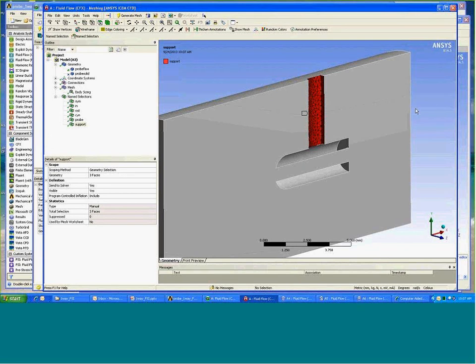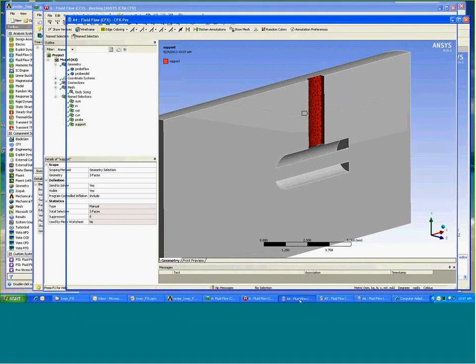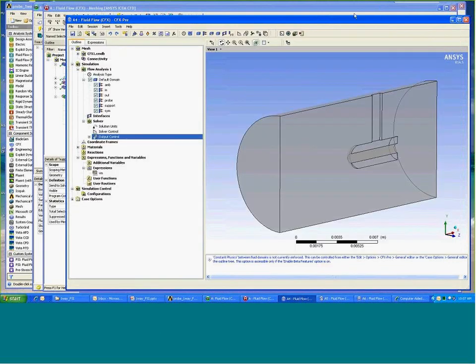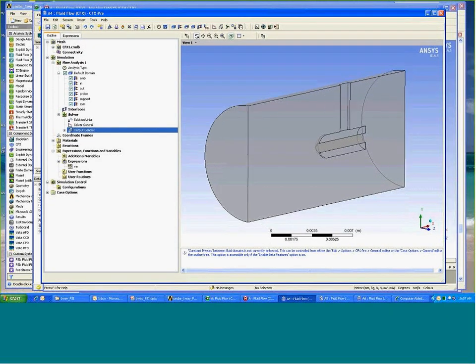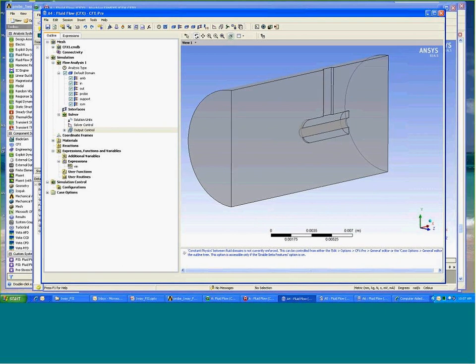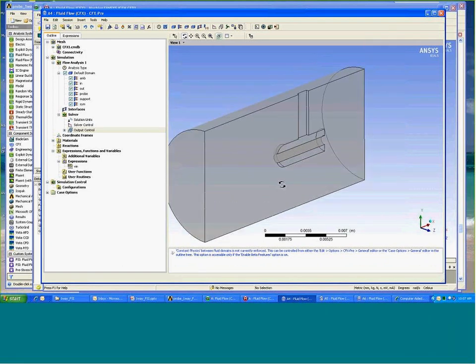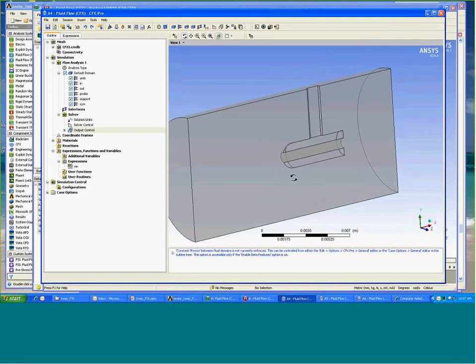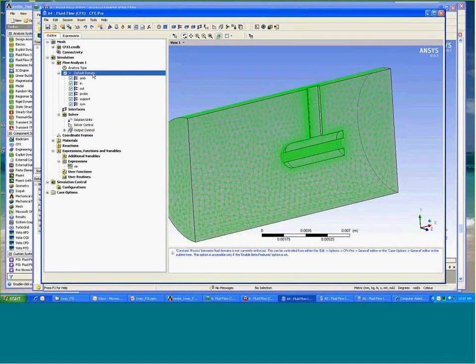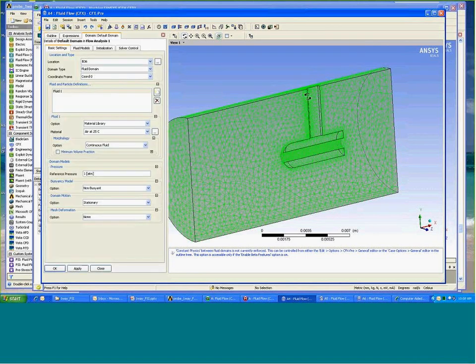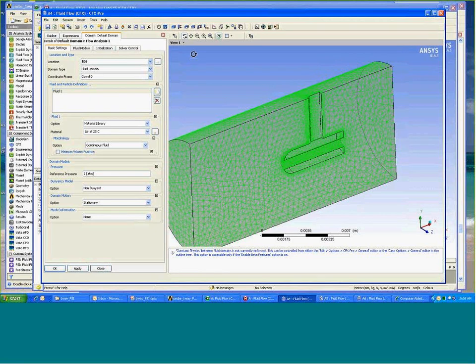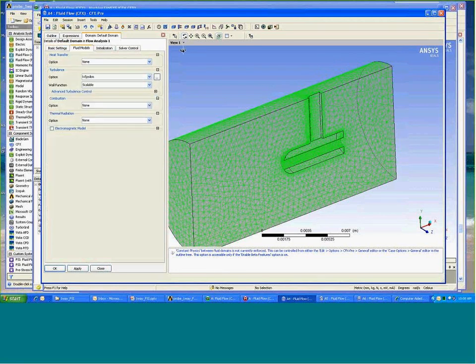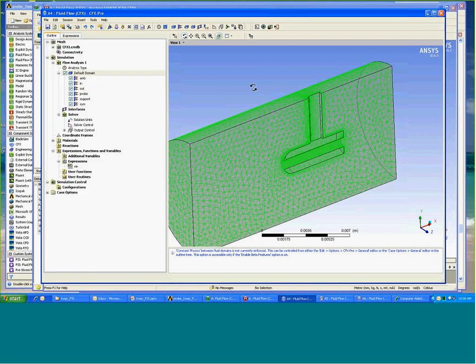So in this case, once the meshing component is completed, we'll take that into CFX-Pre. In this case, we use CFX as the CFD code, and I'll walk you through the quick setup. The default domain is air at low speed, and we pick the default turbulence model in this setup.